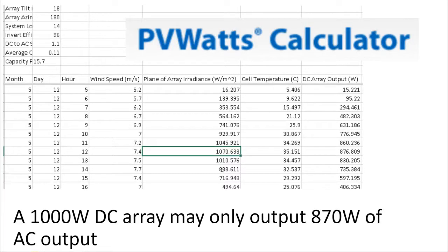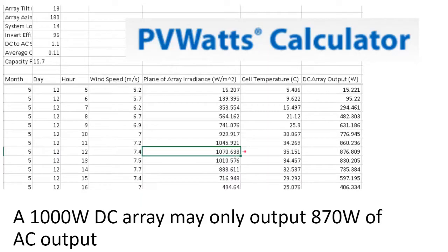How do you determine how many solar panels go onto a particular circuit when they are wired up to a particular inverter? Inverter manufacturers provide online software to assist this design process. They take the specific information from the module specification sheet, such as the voltage, amperage and temperature coefficients, and use that information to suggest configurations which are compatible with their product. Close examination of the PVWatts data can tell us the maximum inverter size without overspending on inverter capacity. Typically, inverters are 10 to 20% undersized compared to the solar array nameplate capacity, although oversizing as well as significant undersizing is not unusual.